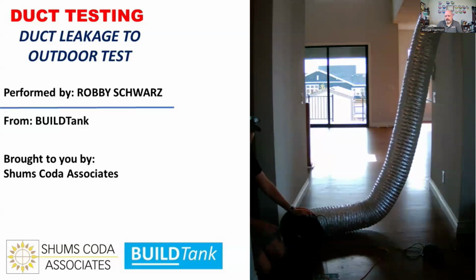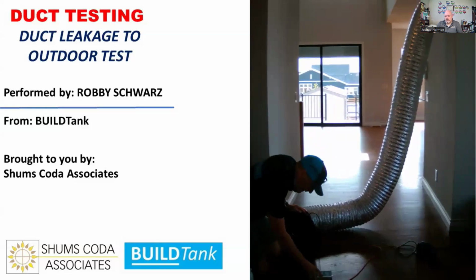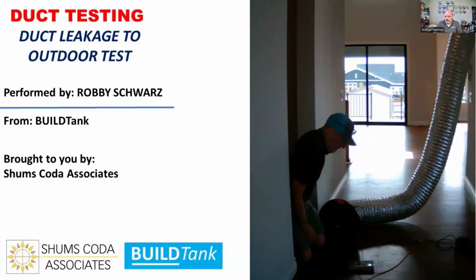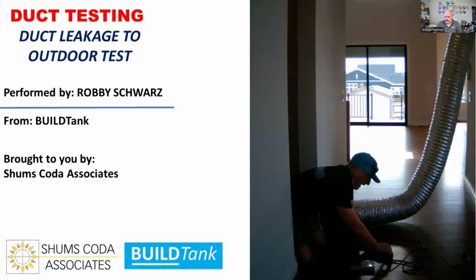If I have a pressure in this duct, and I have a very small pressure, I'd be able to accentuate that pressure by adding a ring here. And that pressure is about negative 0.6 pascals of pressure. So my goal now is to zero out that pressure.